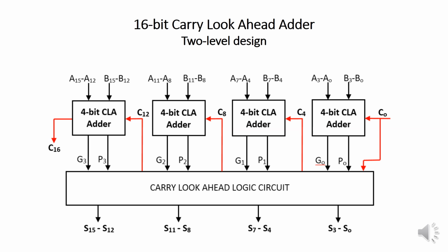So basically, the carry look ahead logic is implemented in 2 stages. 2 levels of carry look ahead are working together, one on top of the other, generating the carries for each block. So, this combination results in a faster propagation delay. The advantage is that for larger values of n bits, more carry look ahead levels can be added. That's how the so-called fast adders are built in many of the recent computer systems.